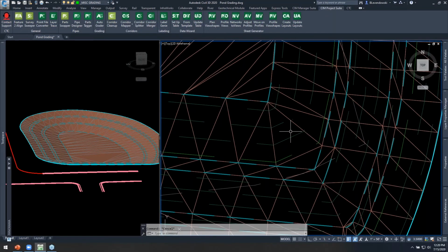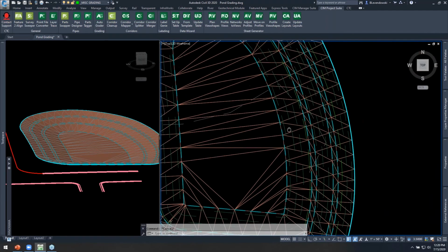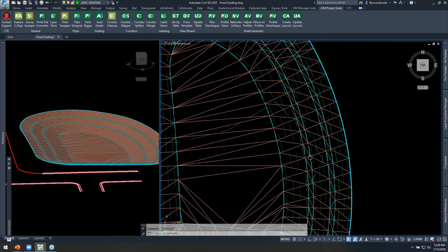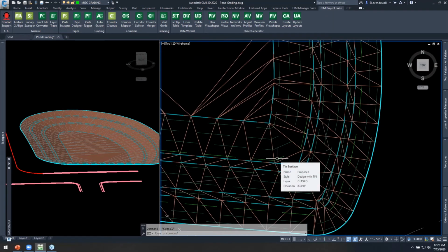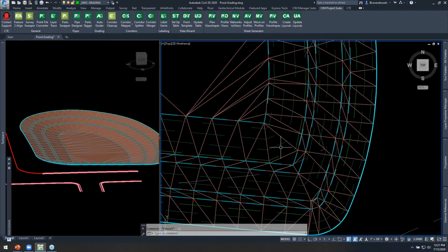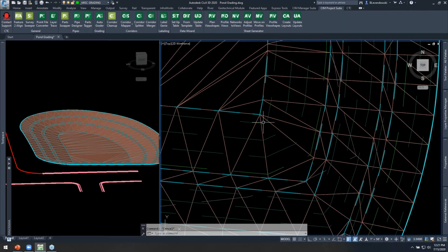Depending on that distance, they may not triangulate right. And so while AutoGrader is going to take care of the vast majority of your feature line grading, you're still going to have these little places where you want to massage your surface or your feature lines, right? So we didn't want to make AutoGrader behave in such a way that you couldn't do any kind of little overrides or anything like that. And so it works real nicely. And so I want to take an example like this one, because it's a nice little trick I like to show people how to control the triangulation.